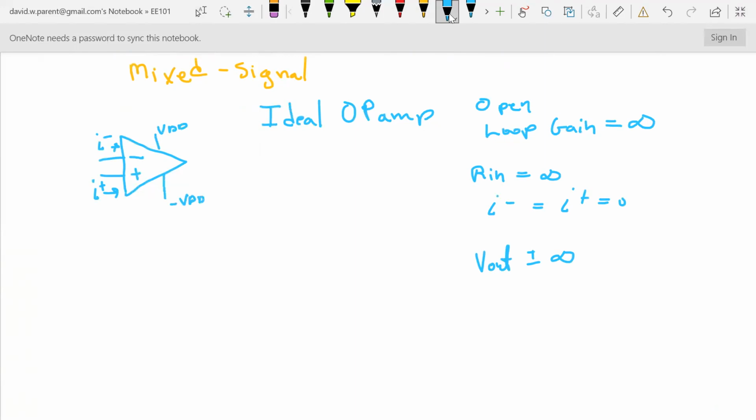If this is minus 15 volts, the signal output can't go any lower than that. In the labs that you've taken, we've designed all the experiments to make sure you never run into any of these problems. But when you're doing something on your own, you could have a signal that gets warped by the fact that it can't go beyond the power supply.